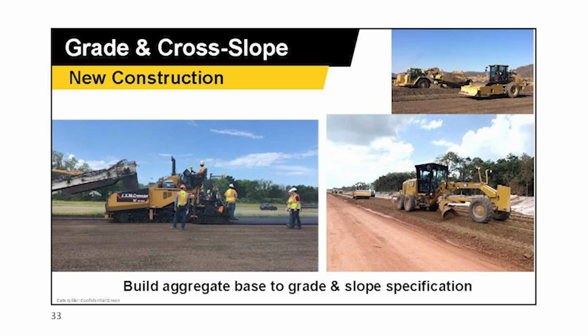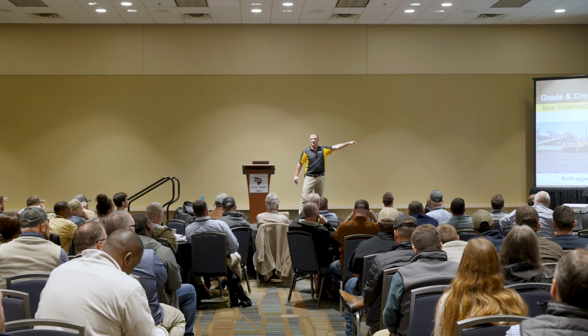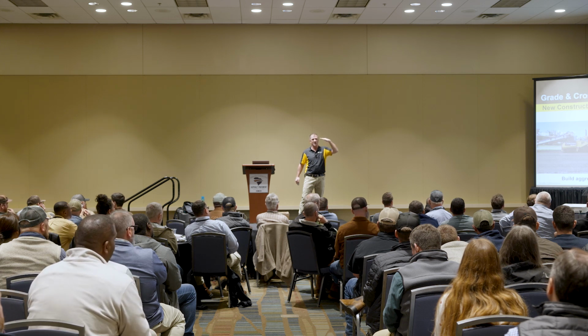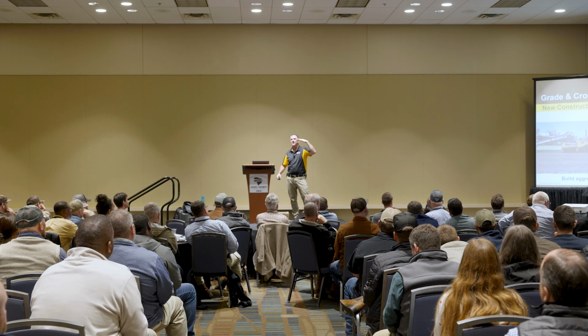So look at grade and cross slope. We've got kind of 3 different scenarios. One of them is new construction. Don't see a heck of a lot of that these days. But whenever we can, what do we want to do for the paving guys? We want to get that base right, to the right profile, right? To the right grade or the right slope. Because when's the paver do its best job? Making a smooth road.